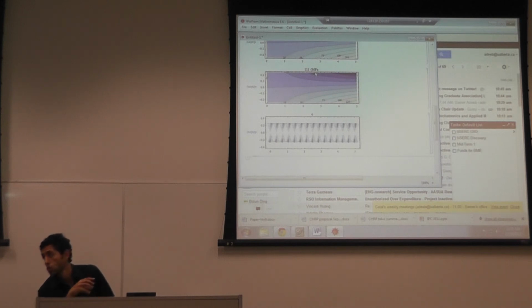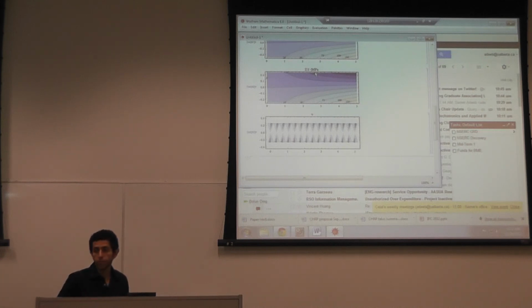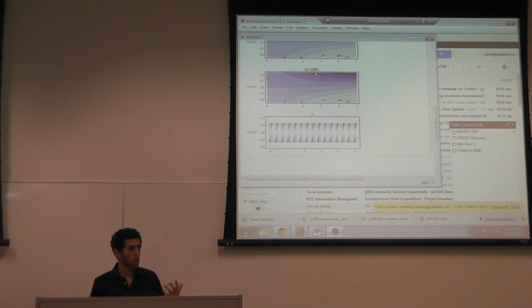Now these nice plots you're producing by hand. Finite element analysis gives you the same plots, but on more irregular geometry, and it's just an extension of this to irregular geometries, and with less restrictive assumptions. There's still some restrictive assumptions in the displacements, but less restrictive. Here, there's very restrictive assumptions, plane sections stay plane, the stress is sigma 11. The only non-zero stresses are sigma 11 and sigma 22, everything else is 0. But in finite element analysis, we do not have those restrictive assumptions.